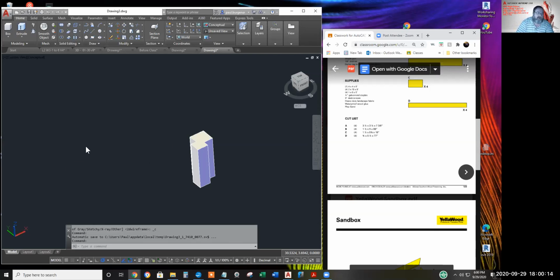Now, depending on how we make the board, we may end up having to rotate it in 3D to get it upright. If we create it flat on the floor, we might have to rotate it on an edge. If we plan ahead with our box command, we can avoid that 3D rotate step.